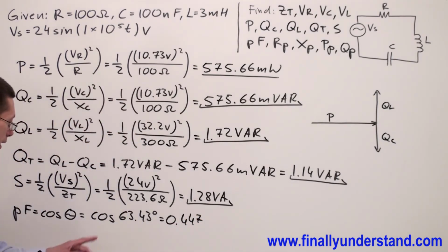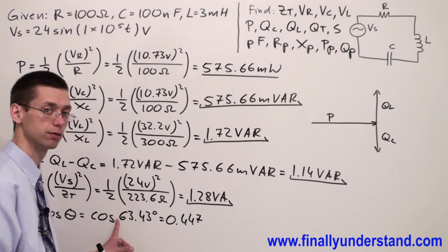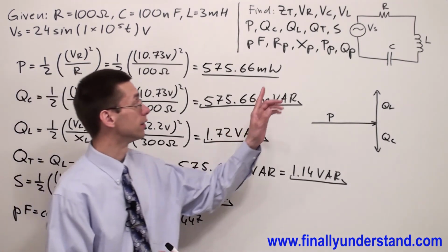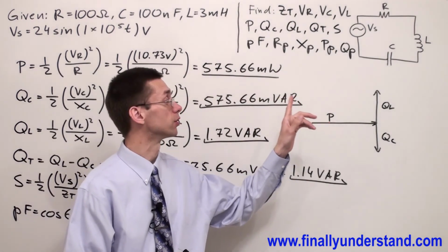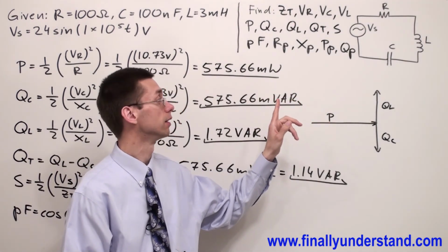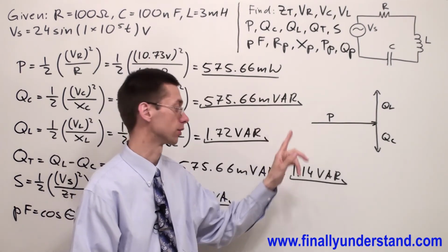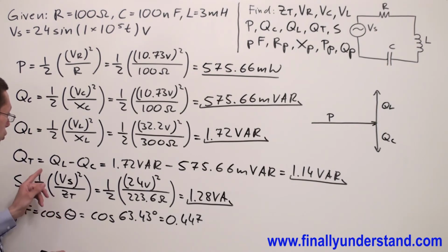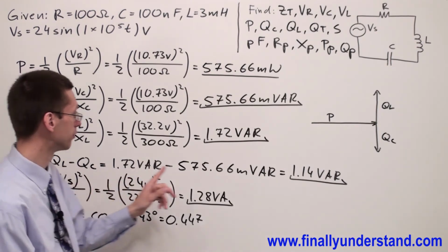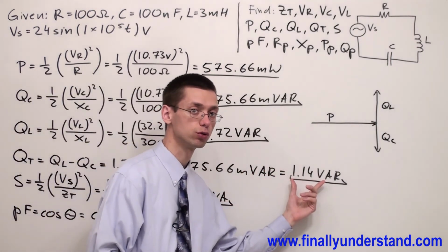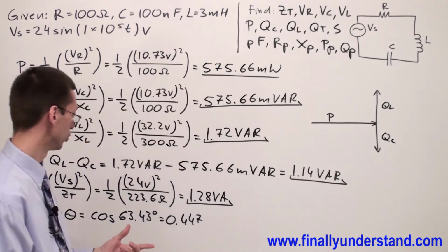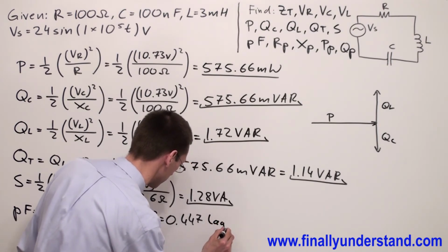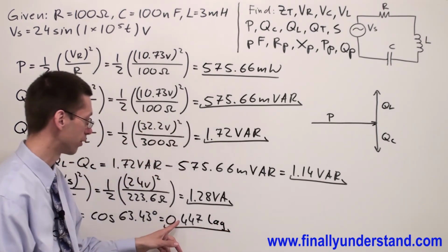Because my angle is positive, or we can say that the inductive reactance is greater than capacitive reactance, or because we got a positive value for Q total, we're supposed to write the word lag next to the power factor.